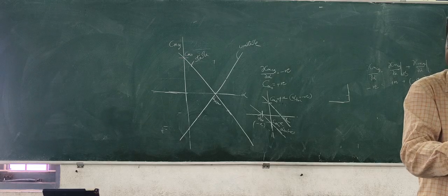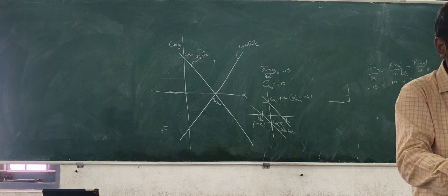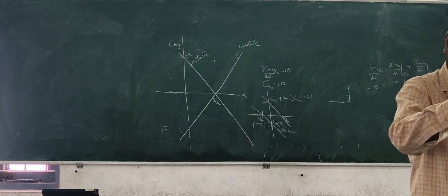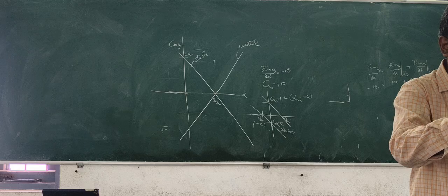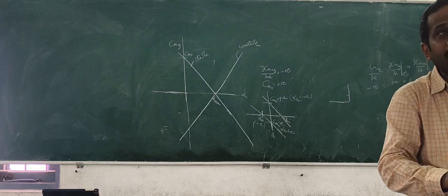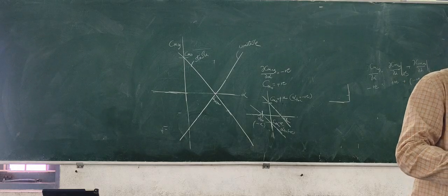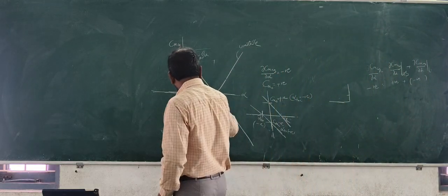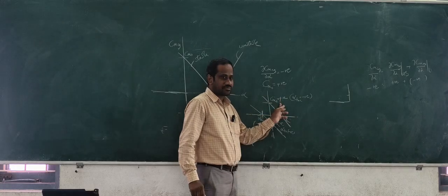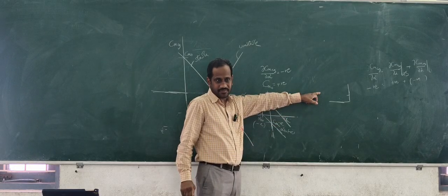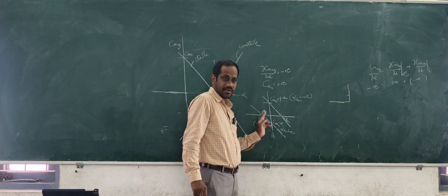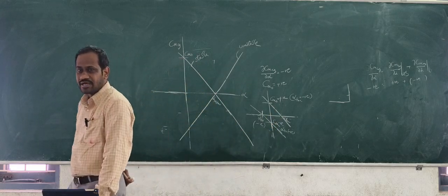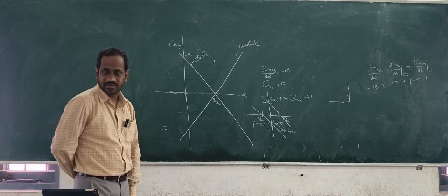If Cm naught is positive, it is a stable aeroplane. If any disturbance is created other than at the equilibrium angle of attack, the aeroplane will always try to look for the equilibrium angle of attack as positive, so that the aeroplane will fly high. Otherwise it will fly low. So that is not a desirable Cm naught, write down. Cm naught positive is desirable. This is undesirable. Both the aeroplanes are stable. Did you get this point?